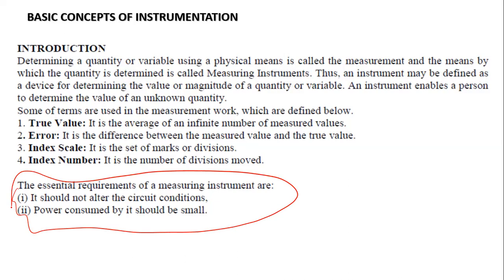For example, suppose you are trying to measure the diameter of a sphere. If the force you exert on the sphere using the measuring instrument is too large, this could deform your sphere, or alter the dimension or the shape of the object you are measuring.